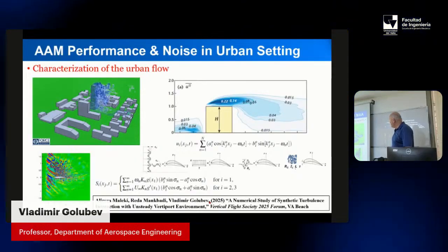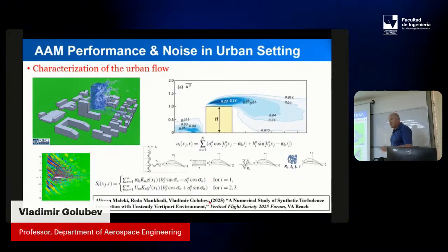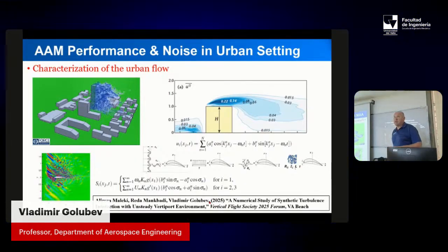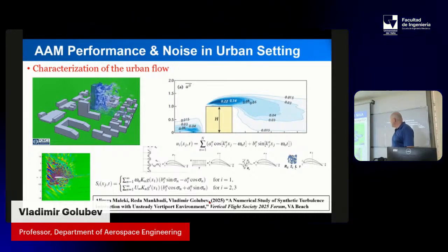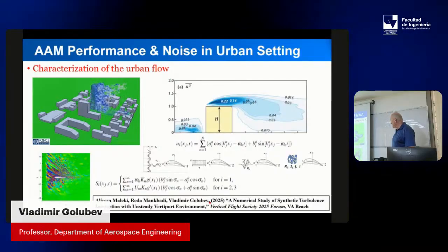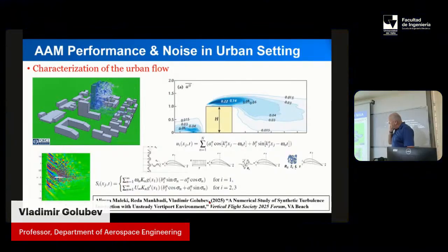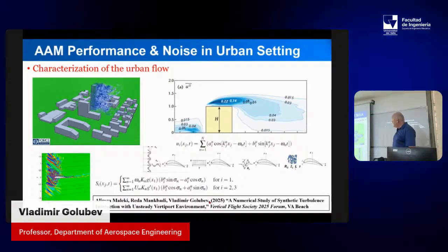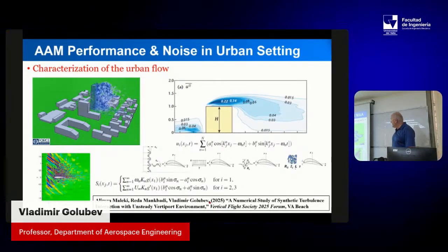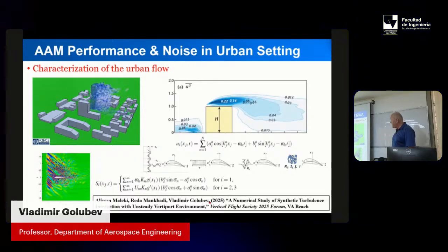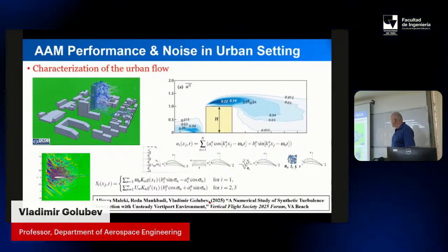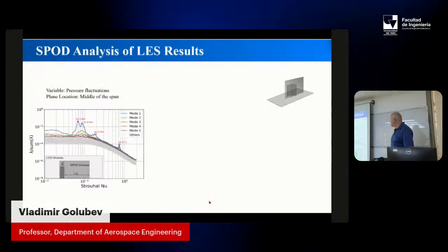We also use our synthetic turbulence model, the synthetic gust model. That will be another presentation. We'll talk about the synthetic disturbance model. That's very important for us because we developed this model using specific momentum sources. And then we can decompose this whole thing, which we predict in the far field, in terms of structures, in terms of canonical disturbance forms, like time harmonic gust, sharp edge gust, vortex, and turbulence with equal scales. So this is the analysis for them.